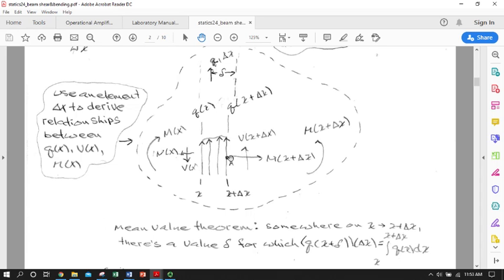Our third equation of equilibrium is going to say, let's make sure that the moment about any point on this body, this little differential body of width delta x, which we're going to take around point A, has got to equal 0. So we don't have to worry about any of the forces that are being applied at A. So this goes away, that goes away. Even though it's shown offset, it's really acting through point A. So what we've got is V sub x, which is going to produce a positive moment about A, equal to V sub x times delta x, because delta x is the distance from A that V sub x is acting.